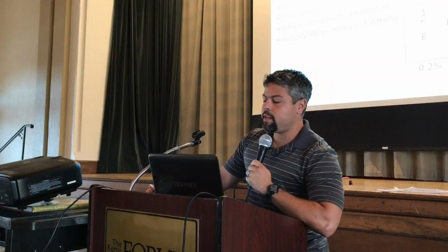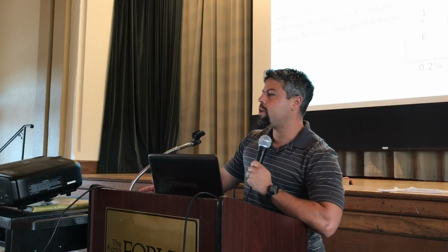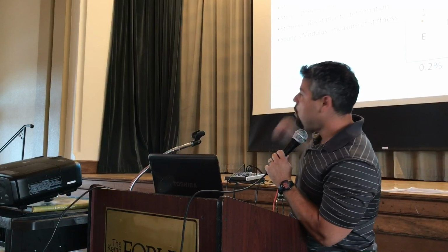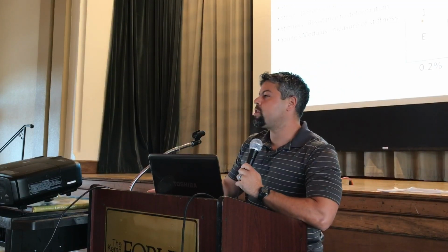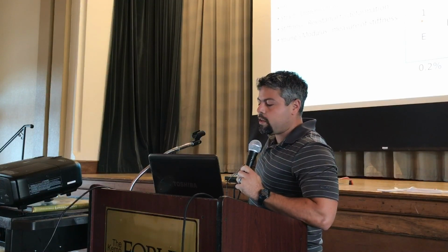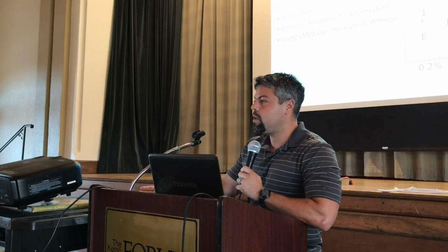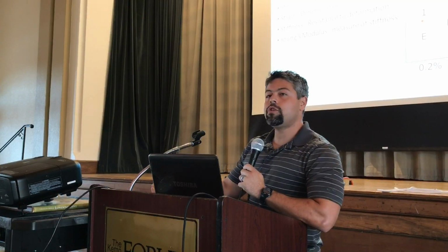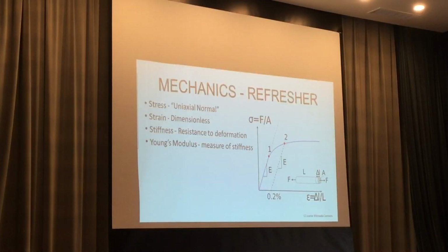Sully talked about this a little bit in terms of how these tissues work as viscoelastic tissues. So when we talk about stress, we are talking about force over area. You see it on the left axis here. Anytime you increase the force on the tissue along its axis, if you look at a cylinder of steel like you have on the bottom right there, you have the increase of force. The wider the surface area, the cross-sectional area of that tissue, the lower the stress on that individual tissue. That seems relatively obvious. It's the same concept for when we contract muscle.